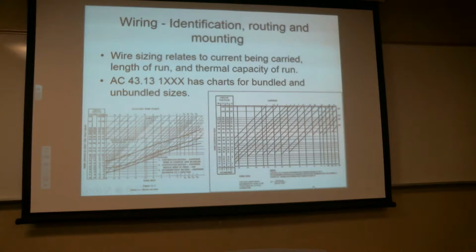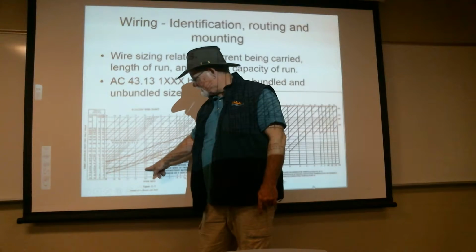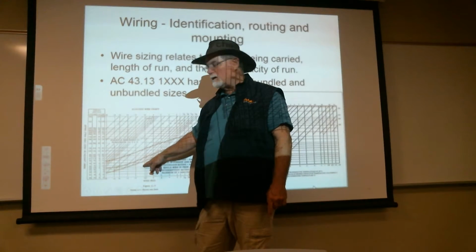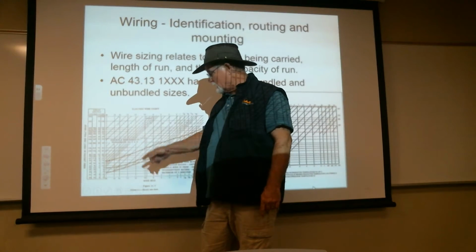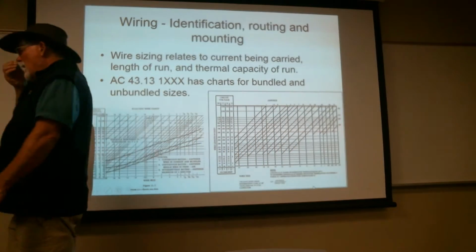And then of course the bottom end of the curves are going to be the maximum amount of current that you can run through any single segment of a wire. So if I was down here, it may well be that I go off the bottom, in which case I'm going to have to go either to less current or much heavier wire.